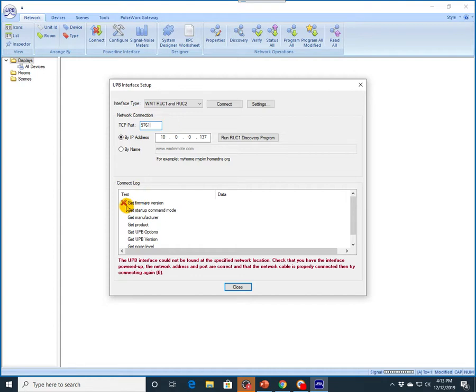When you get this red X, that indicates there's some kind of a problem. So you need to verify your connections, make sure you've got all the cables connected, and you're connected to the correct DB9 port, that your PIM is plugged into the wall and has the serial cable connected to it. Verify you've got power going to the PIM. Look on the left-hand side of the PIM and you'll see a small LED. That should be lit. If it's dark, either the PIM is bad or it's not getting power. So that could be the reason you're getting a red X.